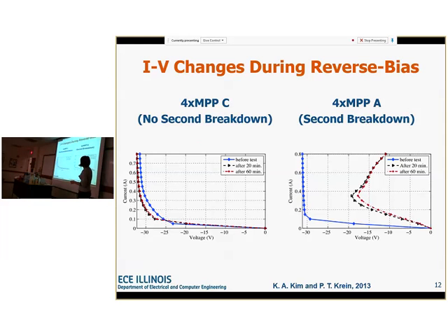This one, we're seeing this weird thing. I remember when I first saw this, I was really confused because I would see this with a few of them, and it's weird. So we're actually ramping up the current, forcing the current up slowly in order to take these measurements. But what's happening, and the IV curve does not actually hook around like this, is as we measure up to here, we're heating up the cell. It's changing its IV curve, and it's becoming like this.